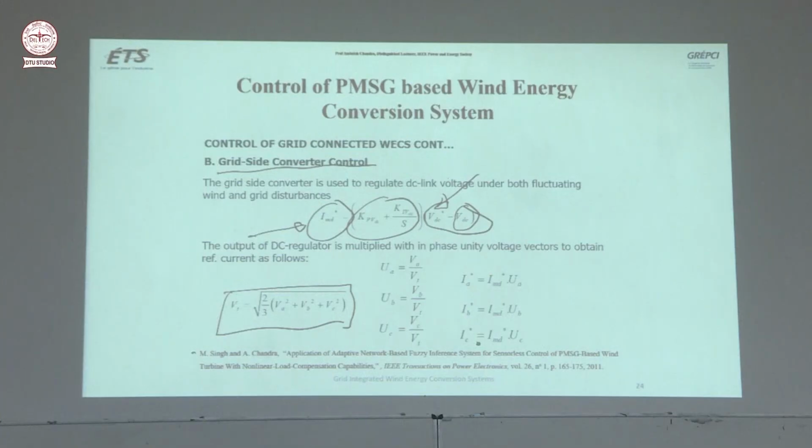And then, like yesterday professor was saying, you are using unit template and there is a problem in unit template, the voltage is distorted. Right, you are right, so that is the right way. But because it is a very simple control, otherwise you can use PLL and those things to get perfect sinusoidal.